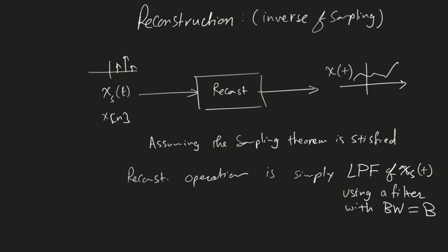So we figured out that in order to perform this by looking at frequency domain, we already found that if we go to those replicated spectrum version of the signal, which happens when it is sampled, if you remove those replicas and only maintain the middle one, which is effectively a low-pass filtering operation, you end up with your original continuous time signal recovered.